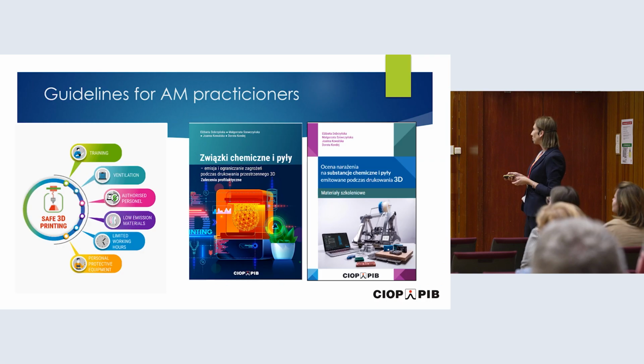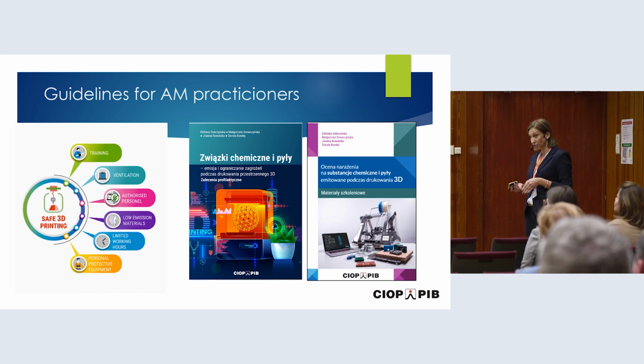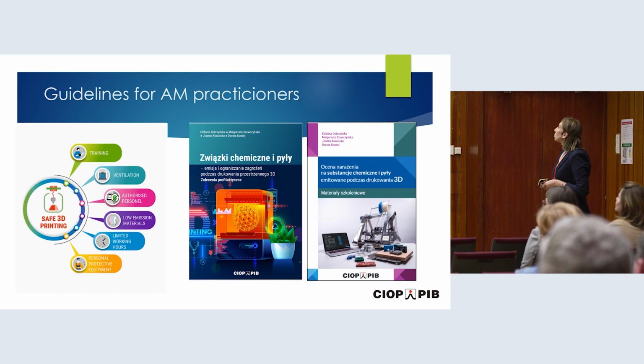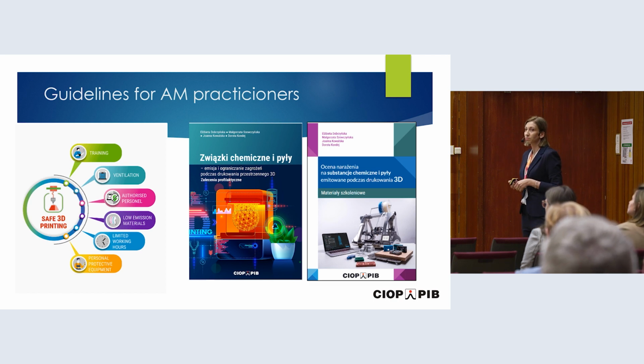And we have also prepared some guidelines for additive manufacture practitioners, starting from the good practices covered by the infographic presented on the slide, which covers the training, ventilation, access of authorized personnel only to this kind of printing, also application of lower emission materials if it is possible, or applying limited working hours for those who carry out the printing activities at work, and also use of personal protective equipment.